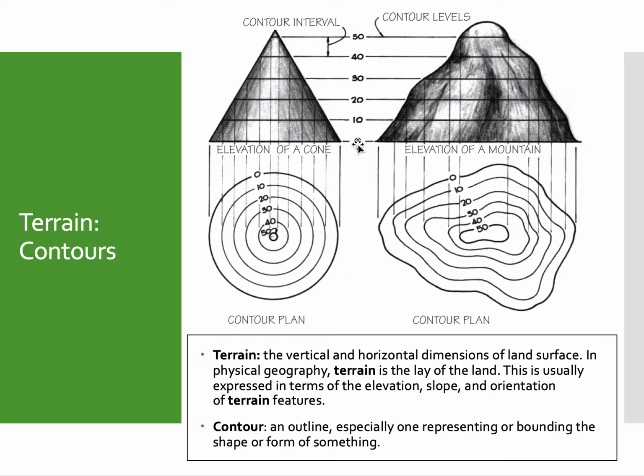Now, if we decided we're going to set our increments at 10 feet, and that is a decision that you make based on the property you have. If it slopes greatly, 10 feet might be too little. You might need to do larger contours, because otherwise you're going to have a whole lot of lines really close together and it may be too much information. It becomes something that as you start working on projects and seeing, you start to understand a little bit better by working with it. It becomes a decision that is made on a project as to where you want to set the contour levels and how far apart you want them. In this case, we're just going to go with 10 feet.